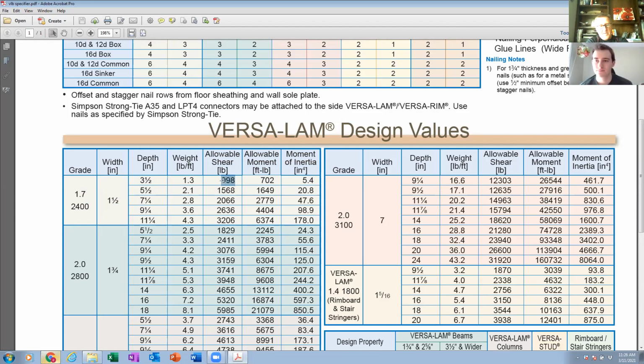So the beam that we just designed a second ago when I was writing on it, 5 feet in, required 1,160 pounds of shear capability. Well, if we don't want to choose a 3.5 by 1.5, do you see what I'm saying? Because it can only resist internally this much force. You see the power in that? Do you see why this is so important? It's not just will the beam break in half because of moment, it's will it slide in half if you put weight on it.